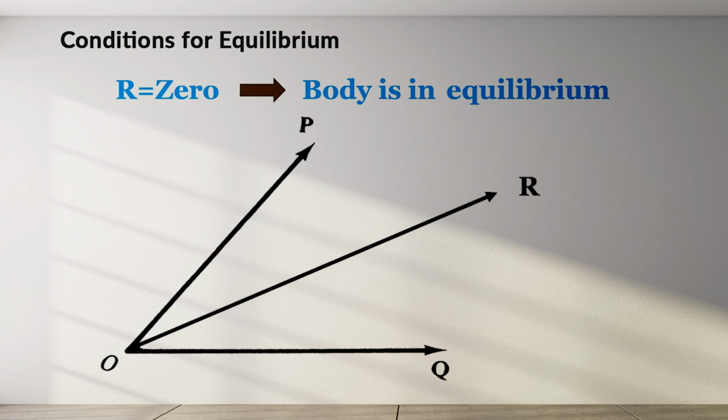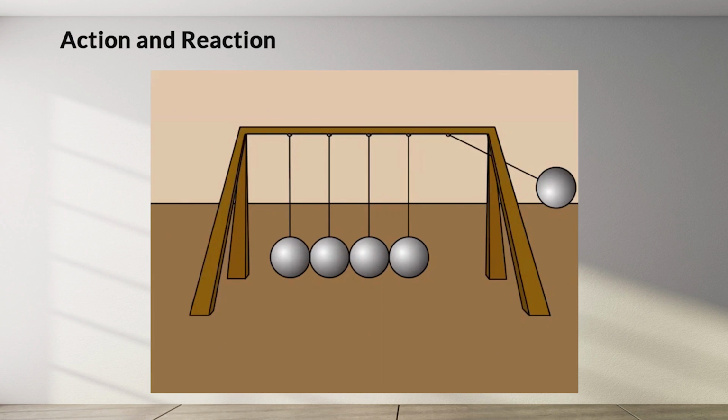Methods for finding the resultant of concurrent force systems can be used to solve problems involving concurrent force systems that act on bodies at rest. In separating a body from its surroundings, we make use of the principle of Newton's third law, which states that action equals reaction. So, if a body A exerts a force on body B, body B exerts a force on body A equal in magnitude and opposite in direction with the same line of action. Newton's third law cannot be mathematically proven. It agrees with intuition. Deduction from the third law agrees with experiment.